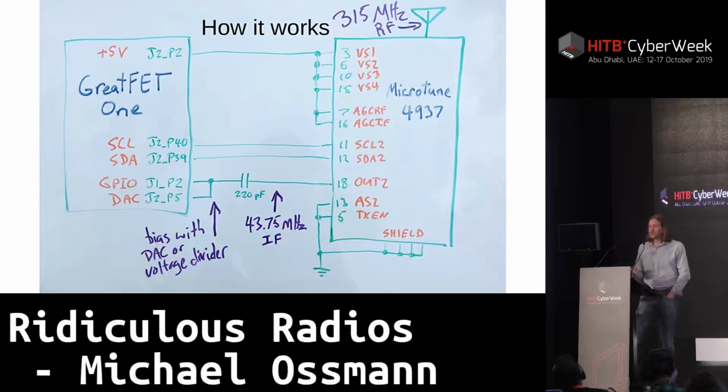We connected the digital to analog converter over to that GPIO signal to produce that bias voltage, that DC bias. And that just let us very slowly change the amount of DC seen on that GPIO pin to get us into the range of that threshold. And once we found that our bits were flipping, then we stopped modifying that DAC value. We just left it there. So that was just a way that we could tune this manually, or automatically, actually, from software.